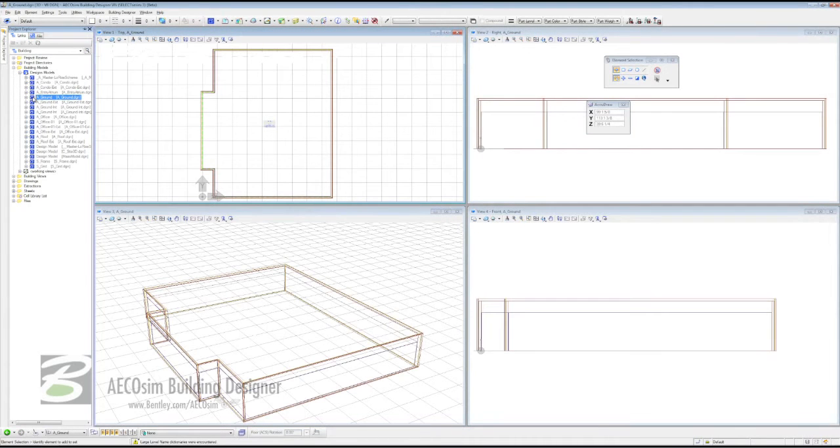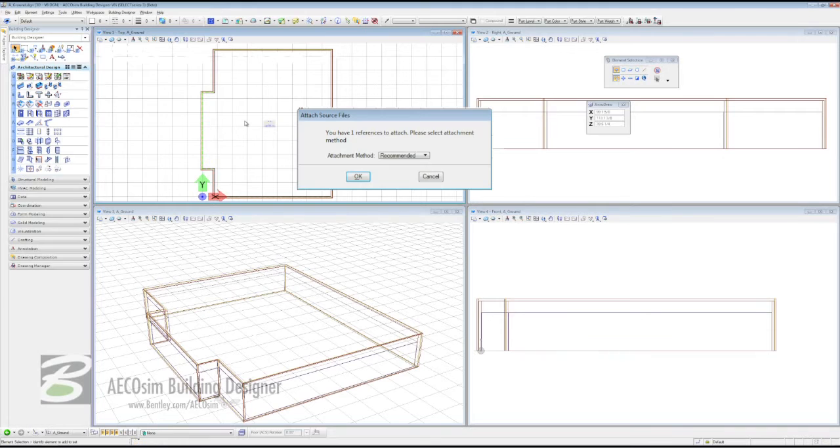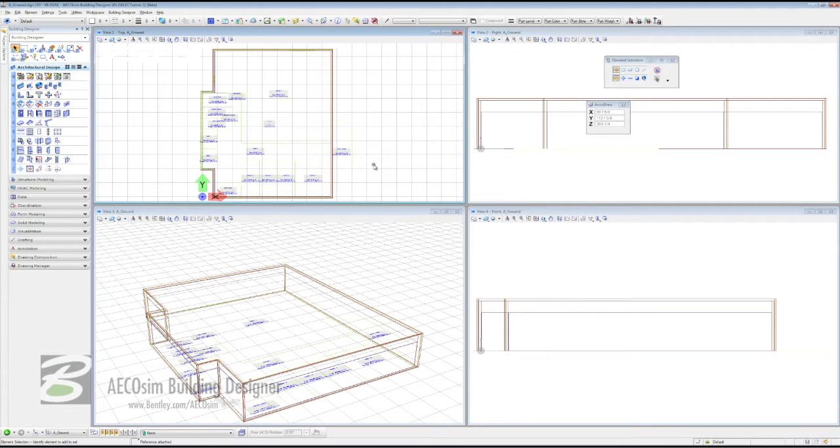Our space planning is immediately swapped out for the file that constitutes some of the ground floor that makes up our master model. And in this particular file, we're going to stay in Project Explorer because now what we're going to do is actually drop in, literally drag and drop in our A underbar ground interior. Simple as that. And our attachment method is going to be coincident. And we're going to click OK. And straight away, literally, instantly, our spaces are attached to our ground floor interior.